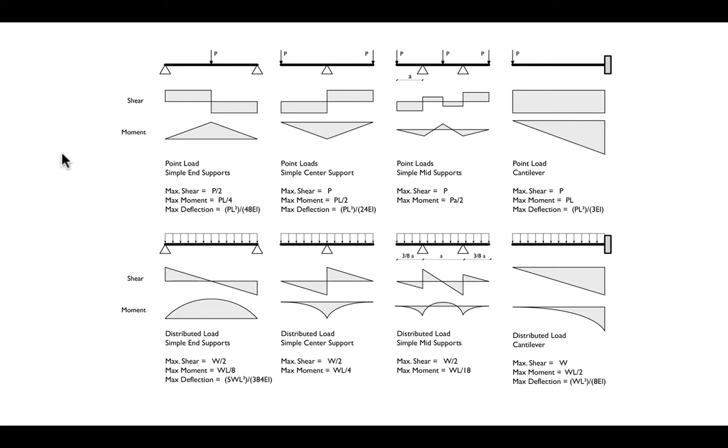So we can design any number of beams for that. And we went through and we looked at how we would select a steel beam. You might remember we looked at the section modulus, which is a measure not just of depth, but where the cross-sectional area of that shape is relative to the neutral axis. And then we sized the beam based on the section modulus that we thought we would need.